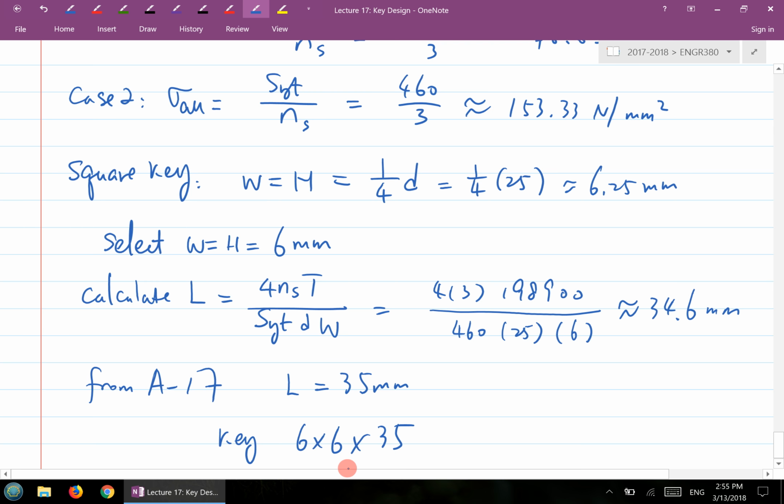Well, you still need to be ready for justifying the size, which basically means you still need to do calculations whether the size or whatever shape that you designed actually satisfies the stress condition. And these formulas are based on the calculation. So if you have the actual loading condition, you pick this size, and then you guarantee that the key will be safe within that working condition.